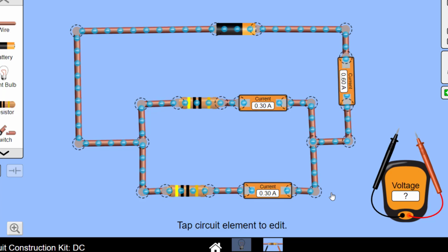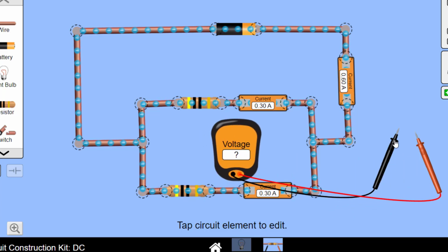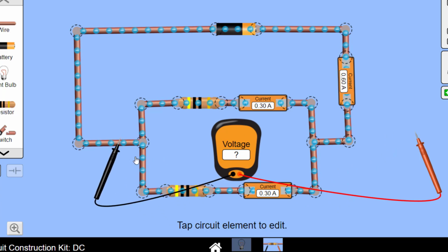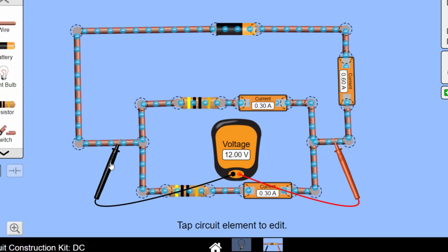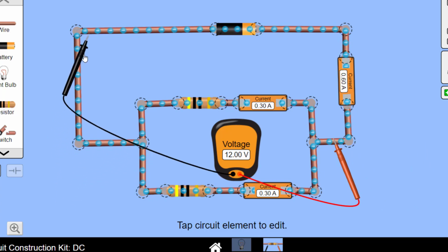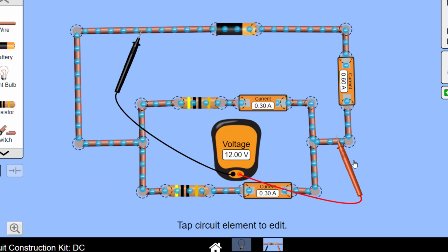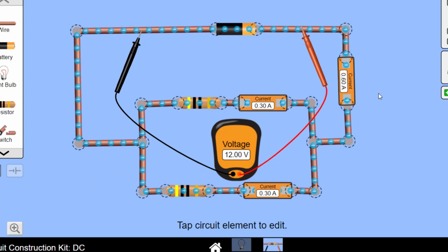So the current entering the branch is double the current in each individual branch because both resistors are the same. Now the biggest problem is, what about the voltage? Well, we can measure the voltage using our voltmeter, and first of all we measure the voltage across the branch. That's what we've been asked to do here, and you can see it's 12 volts. Why is that? Because if we follow the wire around, we get the same voltage because it's connected to the same terminals of the battery.